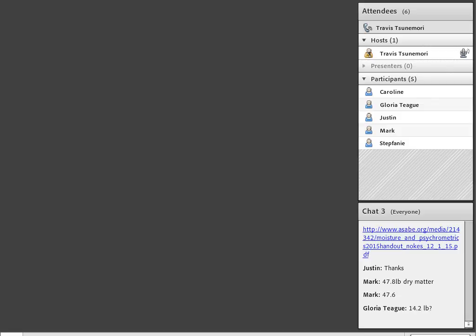Okay, the amount of fruit residue dried per hour. Now, this problem is different than the grain because we don't have anything like a standard bushel. So we're going to do everything on a kilogram basis. So at 85%, we know it's coming in at 85%. That leaves 0.15 of every kilogram as dry matter.